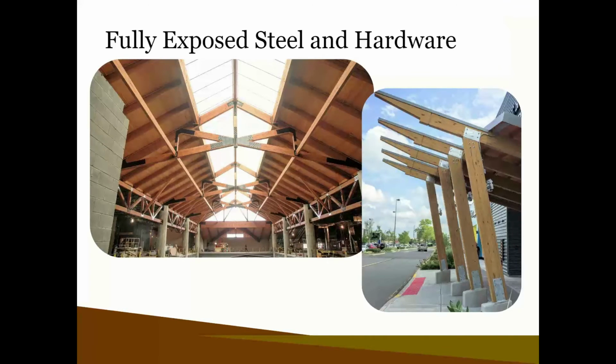Okay, now we'll talk about steel. Steel is an important part of Glulam design. If you can't design it yourself, there's 3 options you can specify so the manufacturer can design it for you. So fully exposed steel and hardware is the first option. That's our default. That's where you have exposed side plates and hardware. This is the easiest to fabricate for, easiest to design and